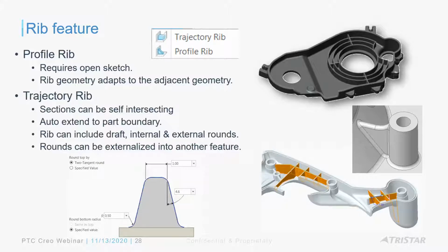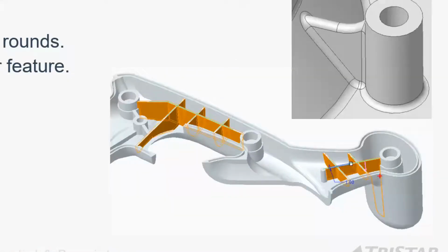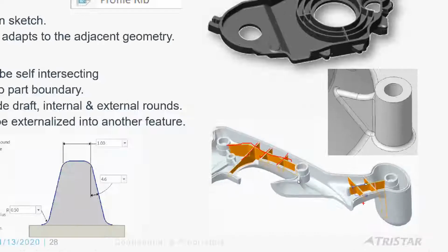It's been there since the Pro Engineer days, nothing new, but something that I've not seen a lot of customers aware of sometimes. A good percentage of the customers know about it, but I thought that would be another thing that you should try out, especially in intricate geometries like this. No need to do any complex quilting or surfacing or anything. All you do is draw your path, right? That's it. And it knows to go to next, both sides right there.